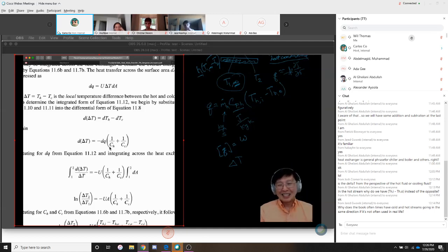But for you to think of doing that, I think this is the hardest part of this analysis, which means it's not that hard. So what happens is this part here. You have the dTC. What is that again? That's the change in temperature of the cold stream. That arises because you have some heat transfer. The heat transfer divided by its heat capacity rate is the amount the temperature has to change by. So that's another way to phrase it.